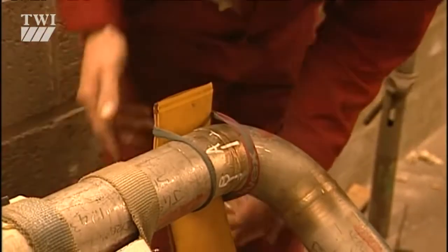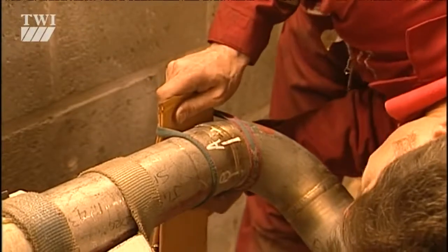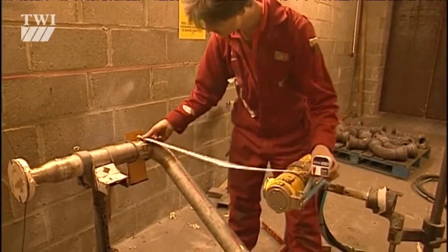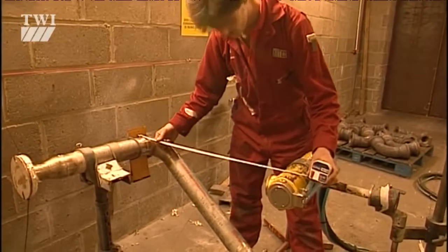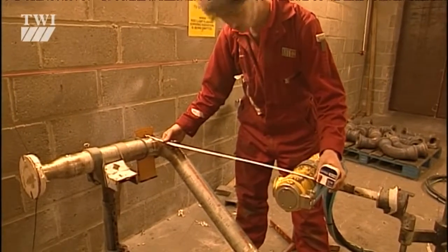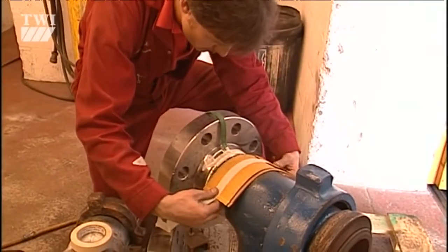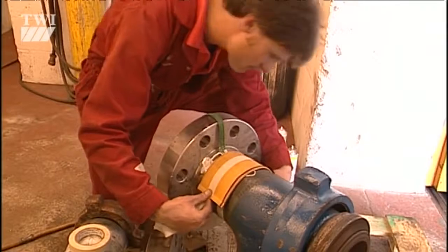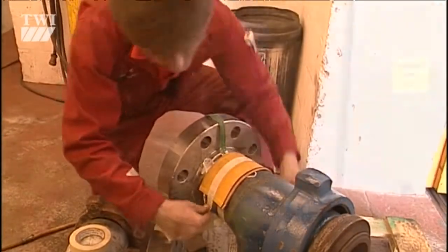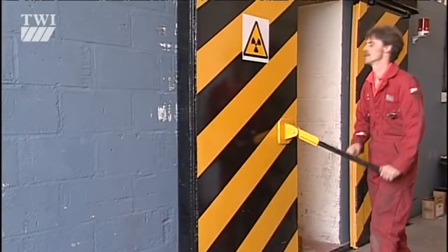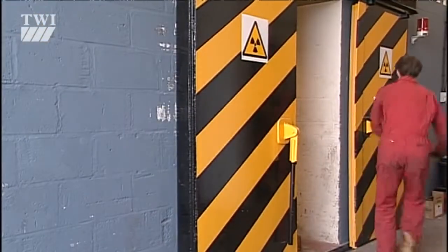For radiographic inspection, there's no need for surface preparation before testing. But you do need to have access to both sides of the component. The film, which is highly sensitive to X-rays, is placed on one side, and the X-ray source is carefully located opposite. The X-rays pass through the component and create a latent image on the film on the other side.